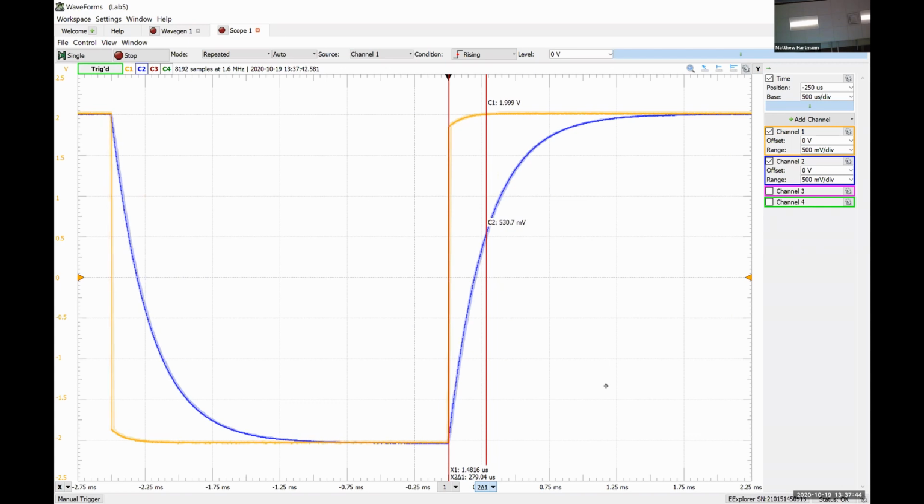Okay, so now that we've got that taken care of, if we go to, let's say, page 4, that's where we have the next things that we need to fill in. I've done all the other work, and we've gotten a 200 hertz, 4 volt peak-to-peak square wave. So first, let's talk about why this is a 4 volt peak-to-peak square wave, when it's obviously got a maximum value of +2 and a minimum value of -2. What does peak-to-peak mean?